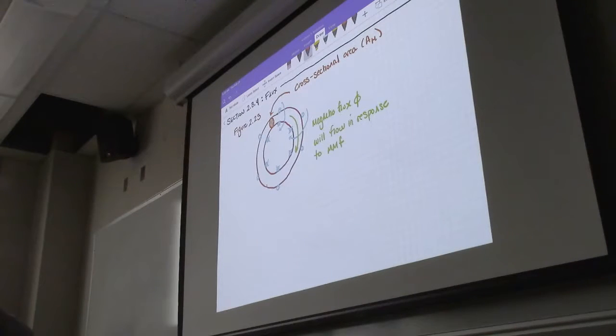Okay, so now we can use equation 2.60 to give us a different representation of this magnetic flux. So we have phi m is equal to the cross-sectional area of the core times the permeability of the core, the ferromagnetic material, times the number of coil turns, times the current flowing through, divided by, remember, the mean path length.